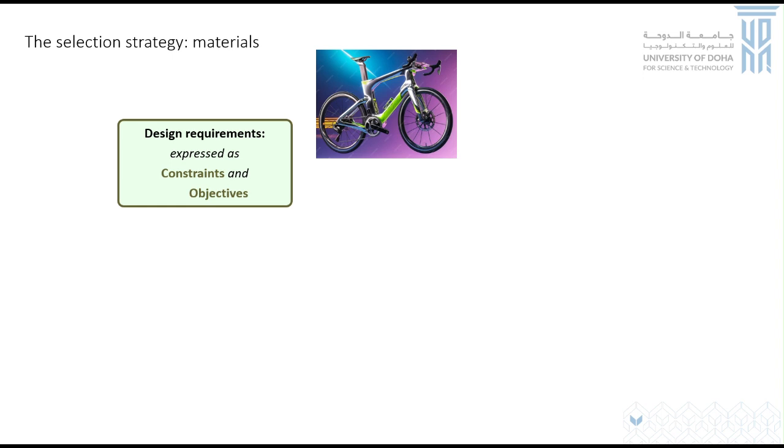So the objective is dependent on the end use of the component, and you have to decide on it as an engineering team, right? The same product for different end uses and different customer needs will mean different objectives. For example, in the motorsport shaft that I gave you as a project, the objective for a commuter car can be that it should be as cheap as possible.